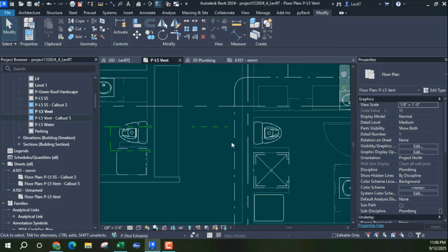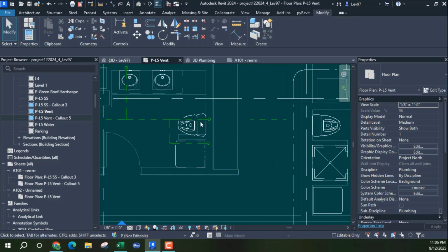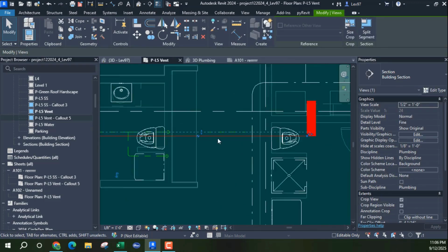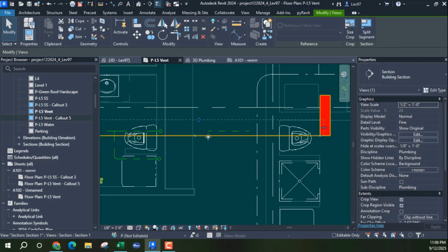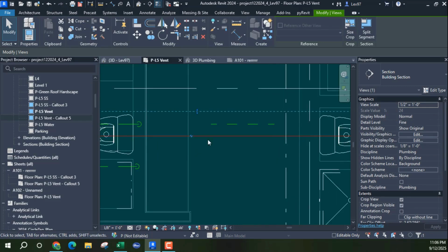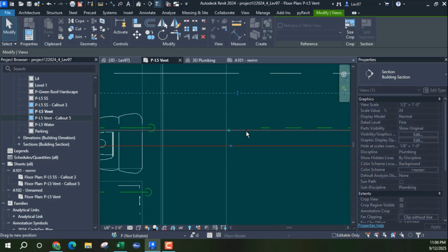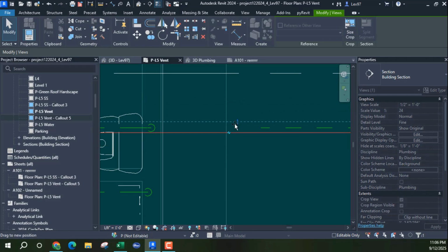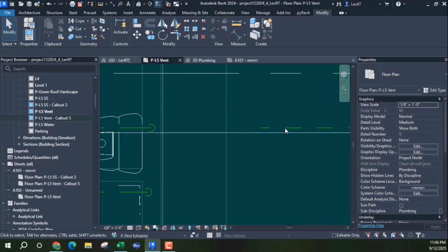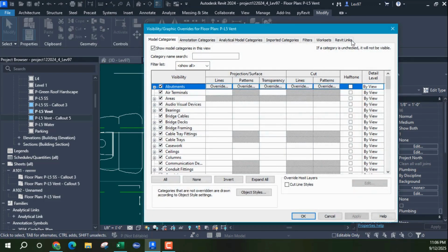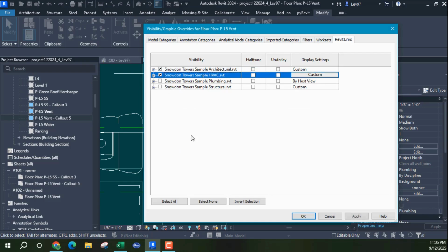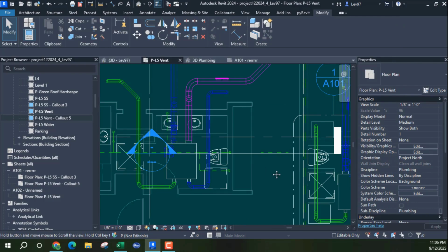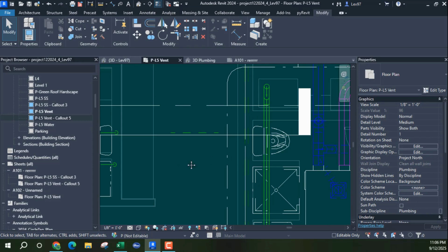Okay, now that's lined up. So I'm gonna come over the top and have this fitting that's going down. I'm gonna change that to a T. That's an elbow now. And I'm gonna let this section view range be very tight, okay? Just in case there's some HVAC in the way. Let's take a look at that. Now I'm gonna look at that on the plan view, and I can see that there doesn't look like there's anything in the way here.